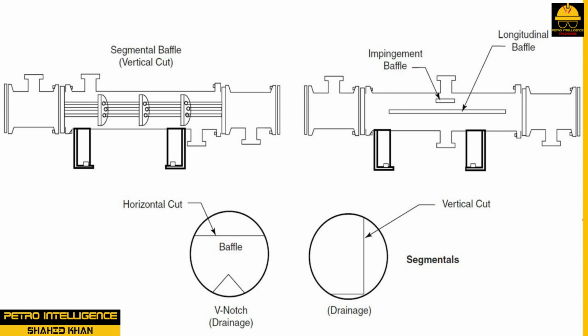For example, a vertical arrangement is typically used in horizontal exchangers used as condensers, reboilers, or vaporizers. Systems transferring large quantities of suspended solids may also use this design. The vertical design allows liquid and solids to flow around baffles. Horizontal baffles are used in vapor phase or all liquid phase operations. This type of arrangement is not used where entrained gases are trapped in the liquid unless V-notches are cut in the bottom of the baffle. Horizontal baffles are used in clean service with notches at the bottom to allow liquid drainage on removal from service.